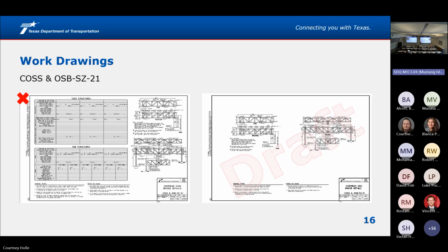Now, if you start going extra long, so your cantilever is over 40 feet, you're going to 50 or something like that, you're going to have deeper panels. You're going to have to majorly increase the sizes. You are now on a one-off design. So none of our standards are applicable unless you want to take them and check them yourself, but you're going to have to sign them as one-off details.